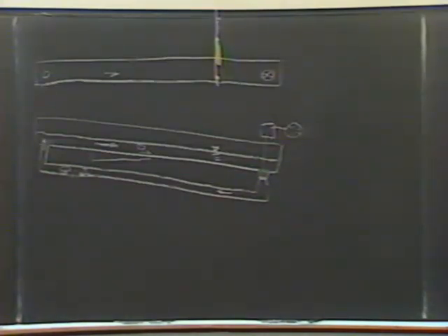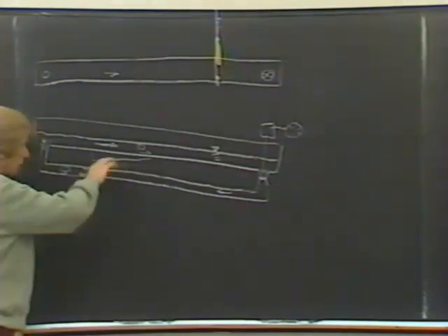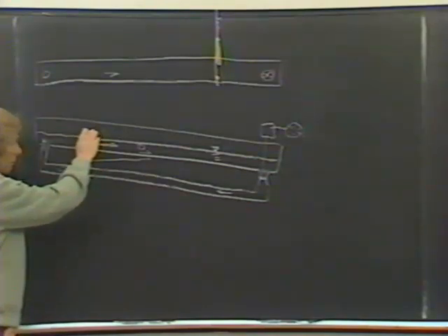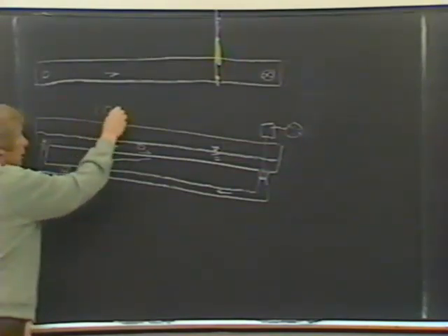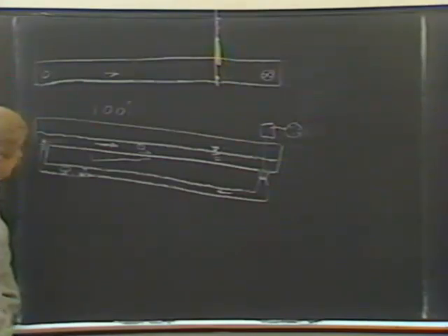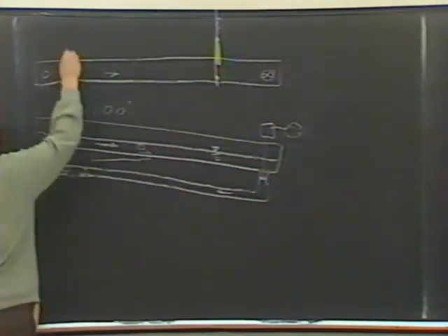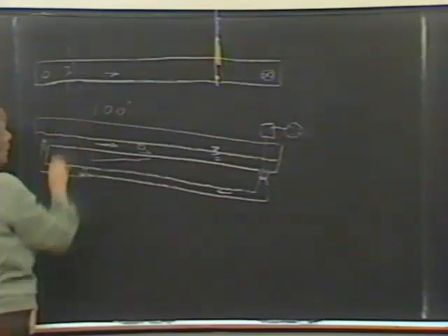Typical hydraulic lab flumes range in size from about 35 feet, say, to, I had one 1,000 feet long. But the 1,000-foot one didn't have adjustable slope. Most of them are on the order of 60 to 100 feet. And most of the studies I'll describe here used a 100-foot long flume, 3 feet wide, and the depth was on the order of a foot.